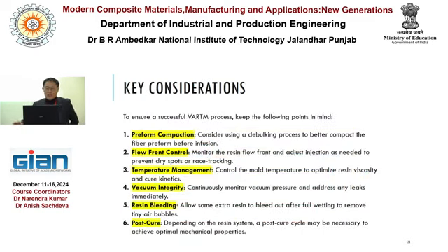So, the key considerations of VARTM, in summary, are preform compaction, flow front control, temperature management, vacuum integrity, resin bleeding, and post-cure. Those considerations must be taken into account. Okay? So each of those, I believe you can quickly understand what those are, right? So preform compaction is